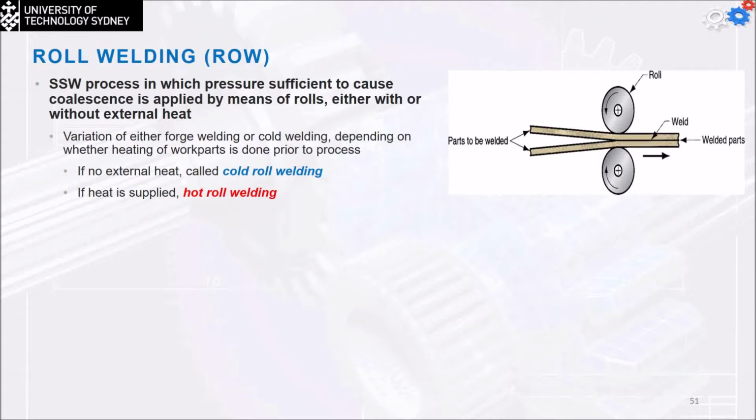The diffusion welding. Now, these are my samples. I'm going to once again pressurize them together but at the same time, again, heat up the chamber. So once again, I added the pressure and heat in this case. So usually it's done in a controlled atmosphere to keep it at a constant temperature with sufficient time for diffusion and coalescence to occur.